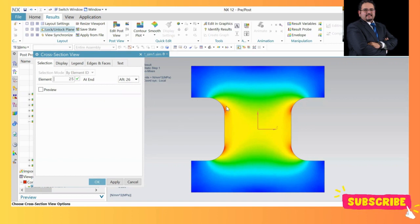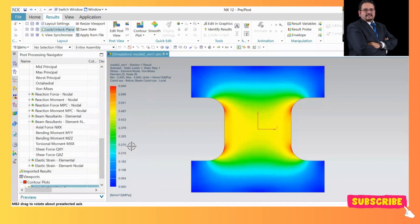A cross section, for example an I-beam, has its own values, right? When you pick something circular, it will change automatically. You can say outer diameter, inner diameter, for example, right? So things are not the same. It will change when you change the cross section. So students, that's basically the second lab.